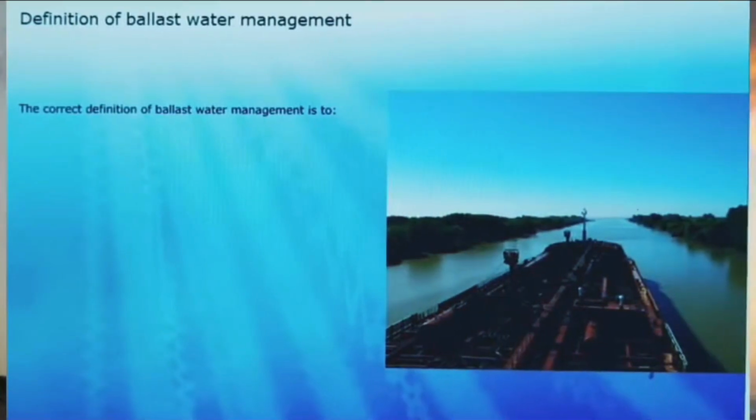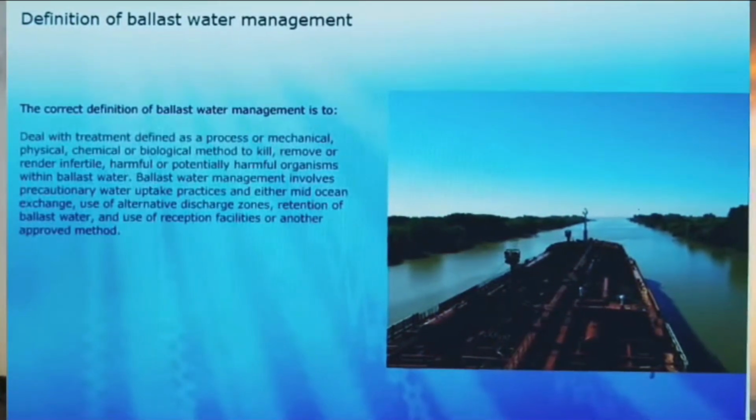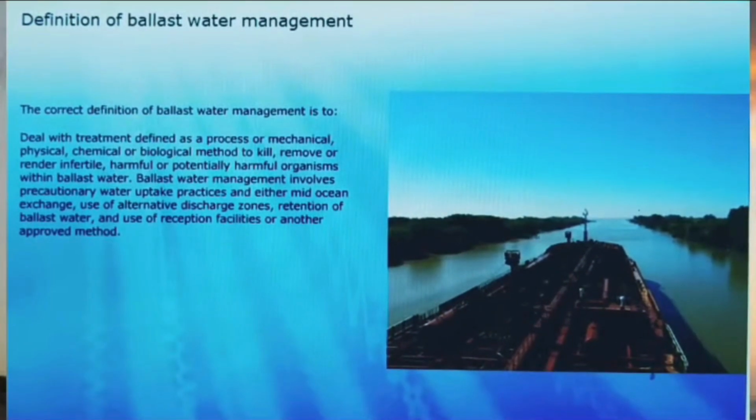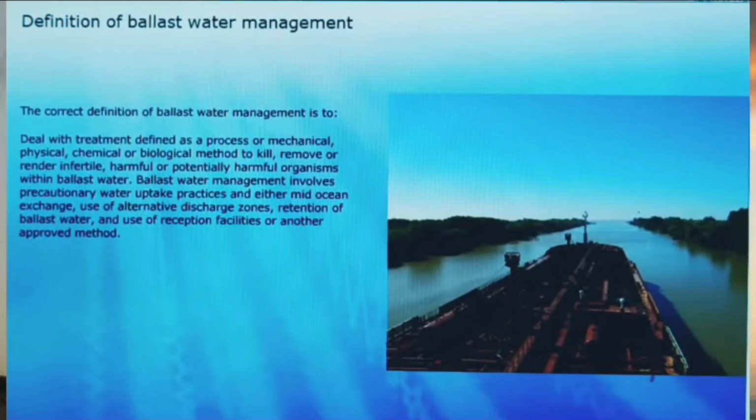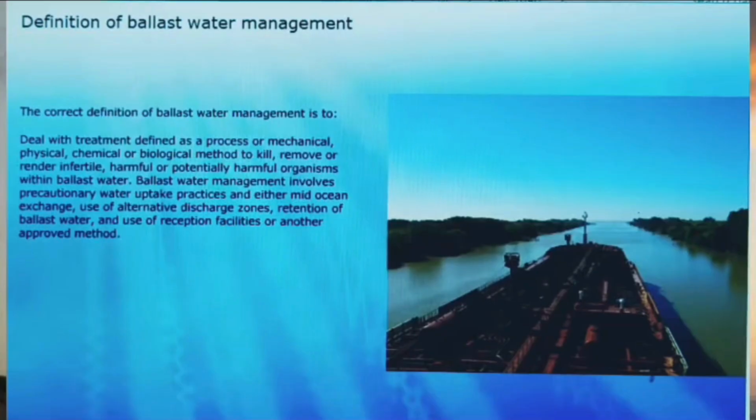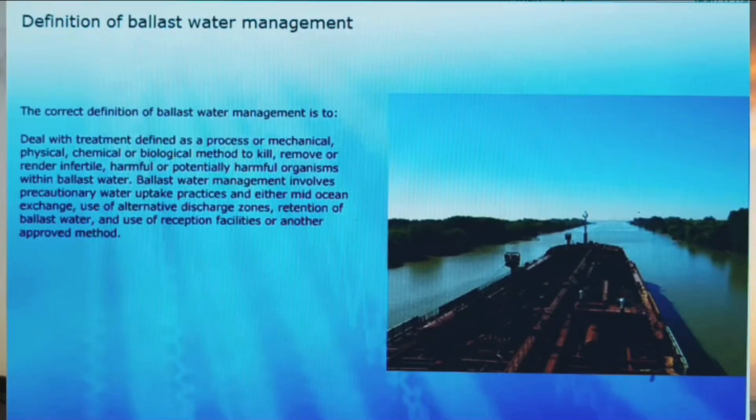Ballast water management deals with treatment, defined as a process or mechanical, physical, chemical or biological method to kill, remove or render infertile harmful or potentially harmful organisms within ballast water. Ballast water management involves precautionary water uptake practices and either mid-ocean exchange, use of alternative discharge zones, retention of ballast water, and use of reception facilities, or another approved method.